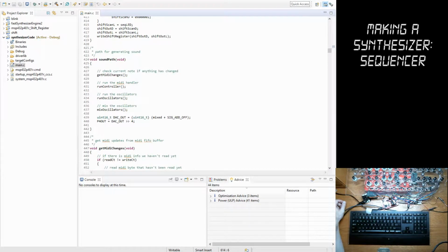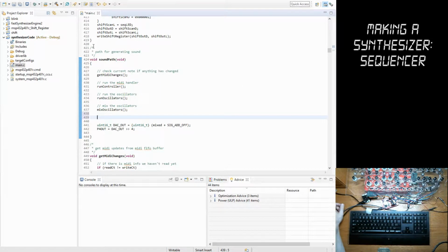Today we're going to be talking about filters, and the filter follows the mixer here. Currently the way we have it set up is we look for incoming changes from our MIDI controller, that's the keyboard. Then we either save those for the sequencer or modify the frequencies for the portamento, pass them off to the oscillators, then mix them together. And the filter takes what's mixed here and filters out some of the frequencies that we don't want. Hence the subtractive part in subtractive synthesis.